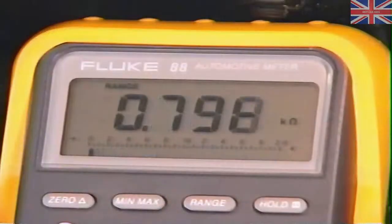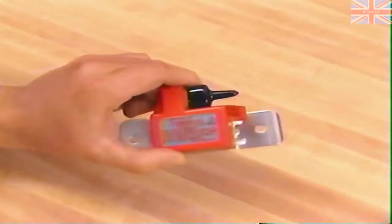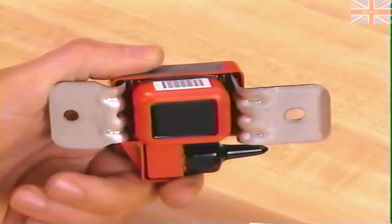If the resistance goes outside of the 2,000 plus or minus 40 ohms range specified for the Stealth, replace the sensor. When you inspect impact sensors on 1991 and 1992 Stealths, look for signs of corrosion on the terminals. Moisture entering through the terminal cavity could be the cause. Impact sensors on vehicles built after June 1992 are sealed with resin to eliminate the possibility of moisture entry.